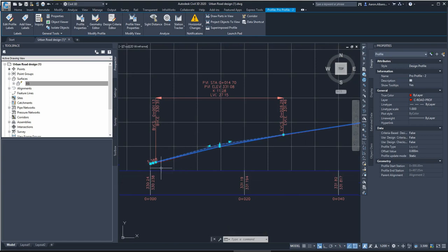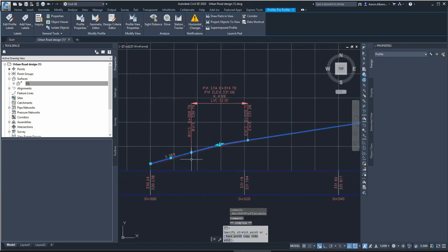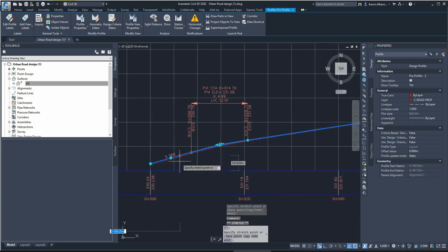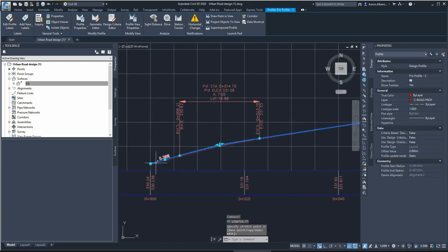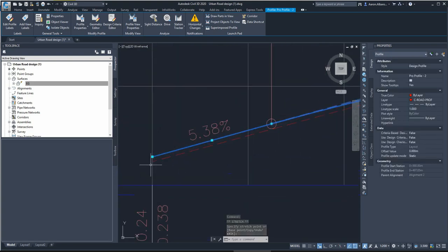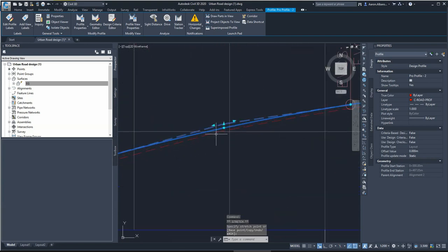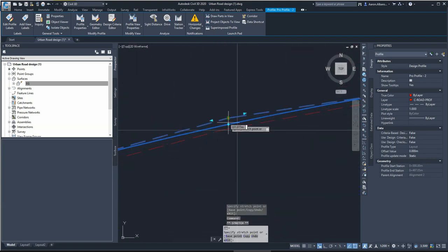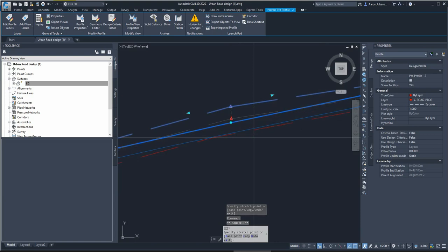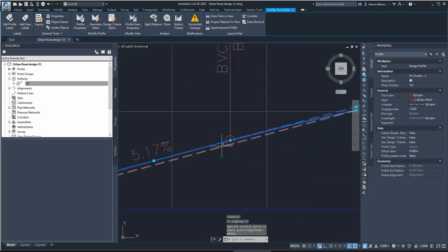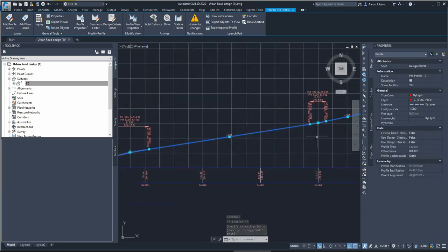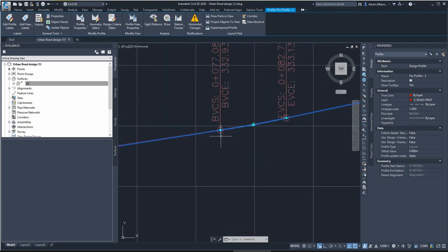Okay, one of the main things, I usually try to keep the curve slightly away from the beginning or the end of the road. We will talk about it later on, because usually the end and the beginning of the road, that's where we will have an intersection. So we usually do some minor adjustment around here. So I just try to keep it away, at least up to 5 meters away from the end or the beginning of the road. That's for the curves. You can't do too much adjustment on the curves, what we can do on the lines.